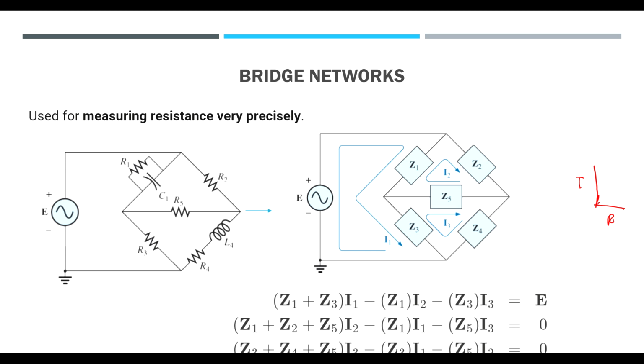At a certain resistance is a low temperature, and when you increase resistance, it's a high temperature. That's how you measure temperature in a lot of cases. So you can say that this particular one is your sensor. Whenever the temperature changes, the resistance changes, and values can be acquired.